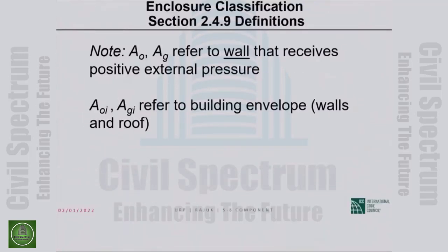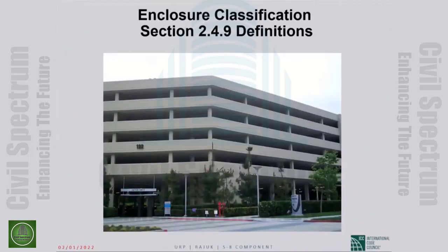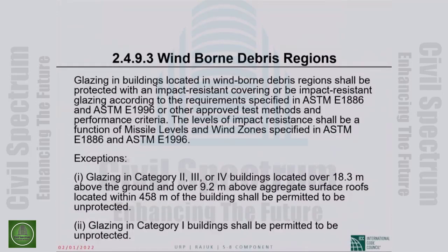and this is an enclosed building by ASCE 7 definition. I absolutely want you to see both pictures. That gas station is an open building, and this parking structure is an enclosed building. Enclosed, again, does not mean a jailhouse without openings on the faces. It simply means it is not a partially enclosed building or an open building by ASCE 7 definitions.